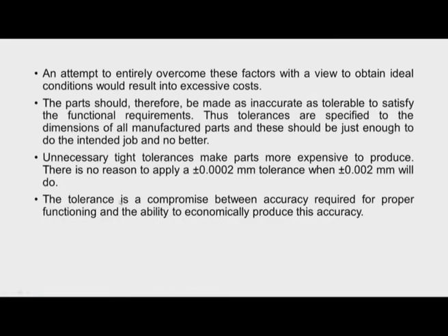Now any attempt made to overcome the factors discussed with a view to obtain ideal conditions, that is ideal dimensions, will lead to very excessive cost. So the part should therefore be made as inaccurate as tolerable to satisfy the functional requirements.